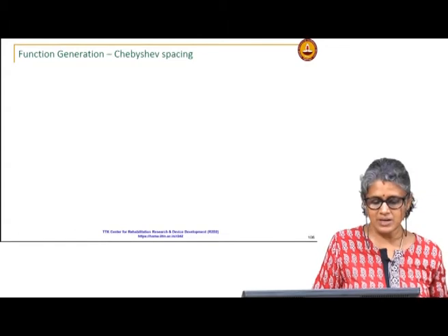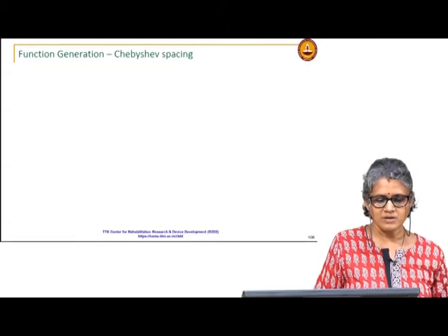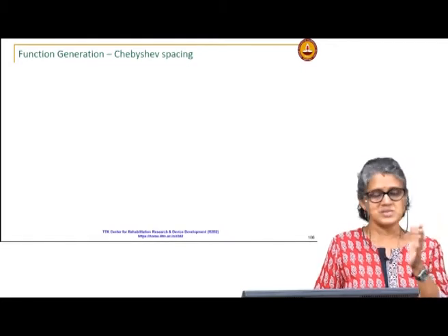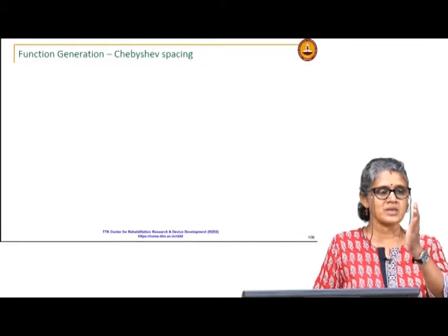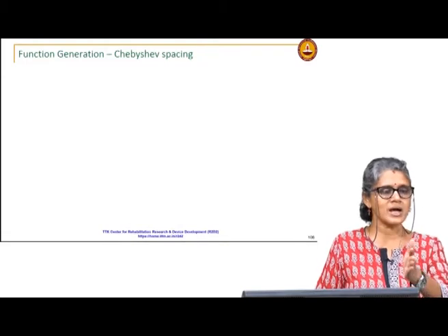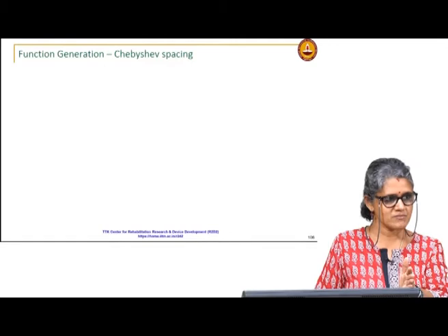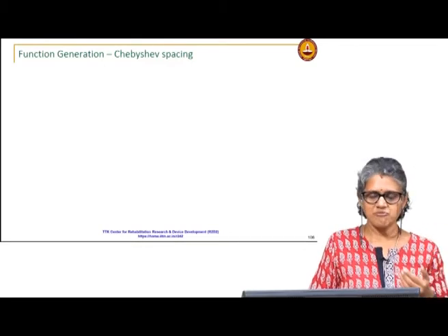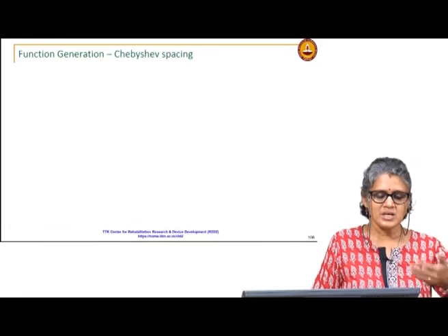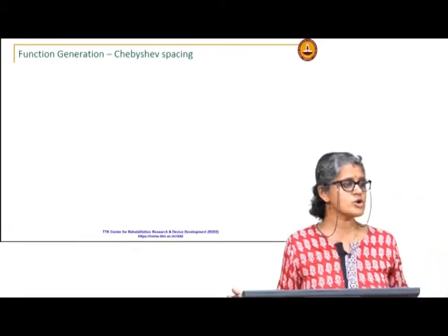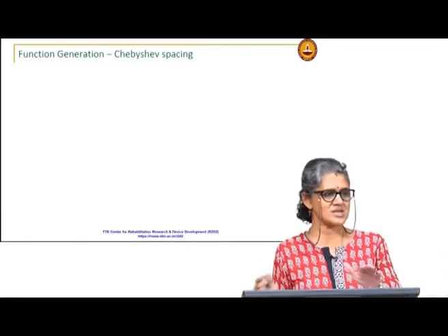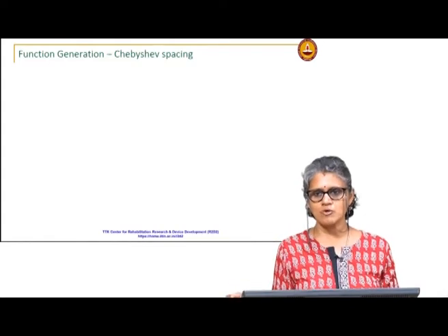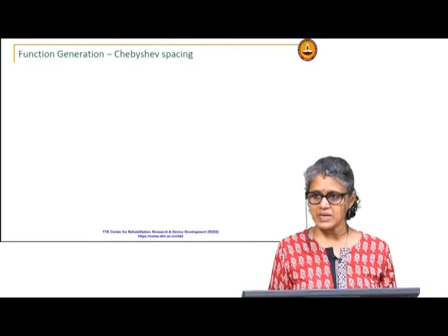If it is path generation with prescribed input timing, meaning at a specific point of the input I want to be at a certain path, versus overall path you look at the normal distance, how far you are. So, the error computation will be more complex than in the case of function generation, where there is an input and an output quantity, algebraic quantities that can be related.